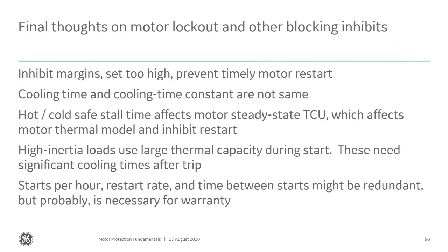So some final thoughts on motor lockout and other blocking inhibits. If your inhibit margin is set too high, that can prevent timely motor restart. Cooling time and cooling time constant are not the same thing. Relay uses the cooling time constant. Hot-cold safe stall time affects the motor steady state thermal capacity used, which affects the motor thermal model and inhibit restart.